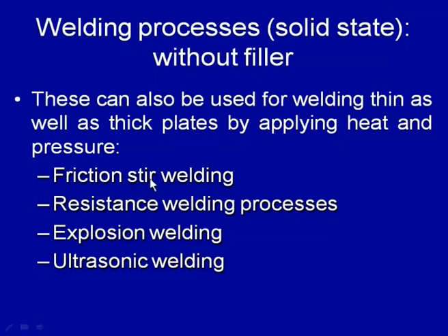state. For example, in friction stir welding, material is heated by frictional heating to about 300 to 400 degree centigrade, where thermal softening of the material, like in case of aluminum sheets, softens the base material, and the mechanical churning along the edges results in the consolidation of the metal and forms a weld joint even in the solid state. And in this case no melting takes place, maximum temperature goes in case of aluminum to around 300 to 400